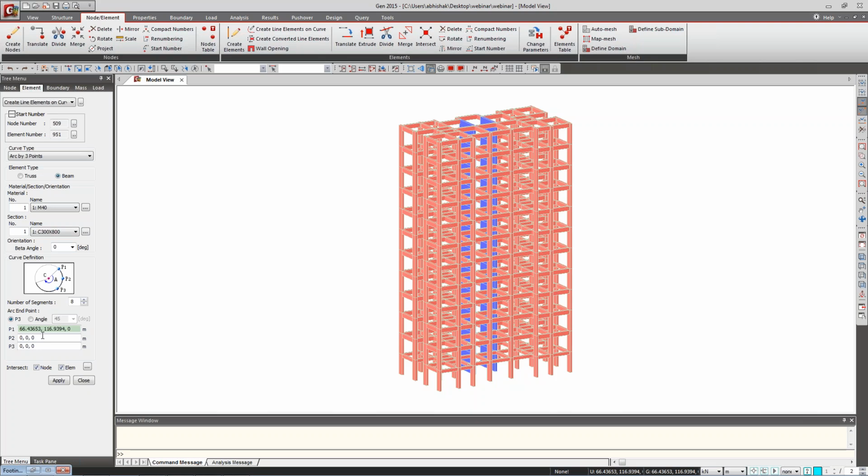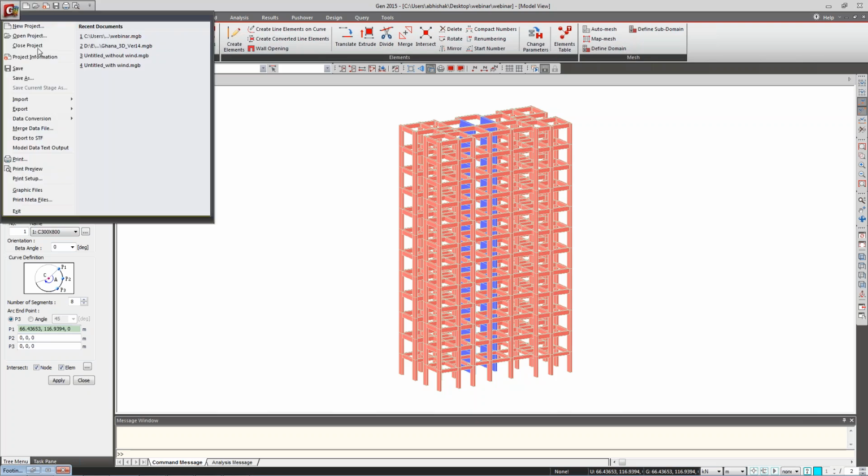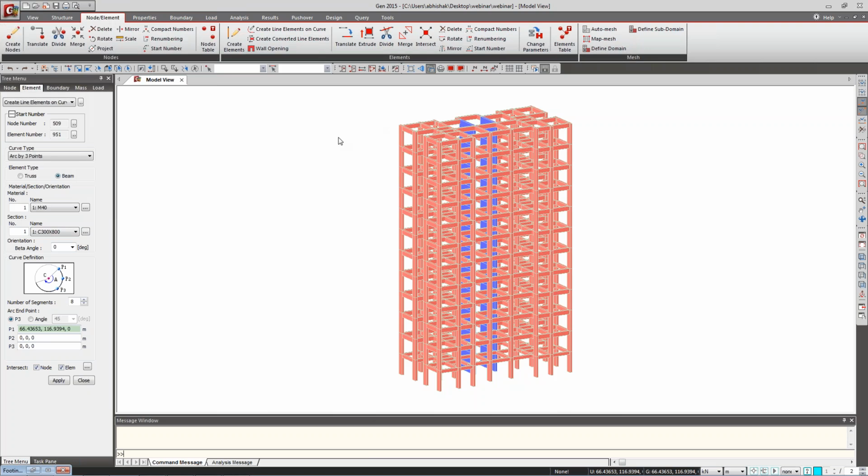Okay, Mr. Ravi Shankar sir is asking one question: is there detailing or an AutoCAD drawing? Yes, the detailing option is there. We have one module, that is the D shop. D shop is used for detailing purposes. You just go to File, Export, and select MIDAS drawing file. Then for that particular file, you go to our next option, the MIDAS D shop. You import it into the MIDAS D shop, and you can directly generate the drawing. It gives the total detailing for the beam and the column. For the wall, it gives only the schedule form, and for the slab you can also define it there.